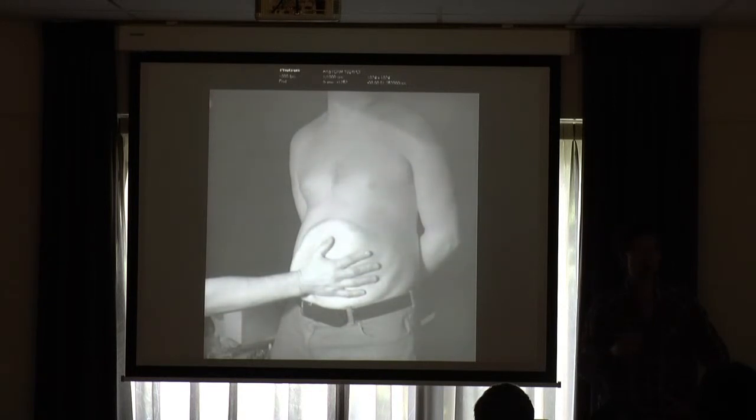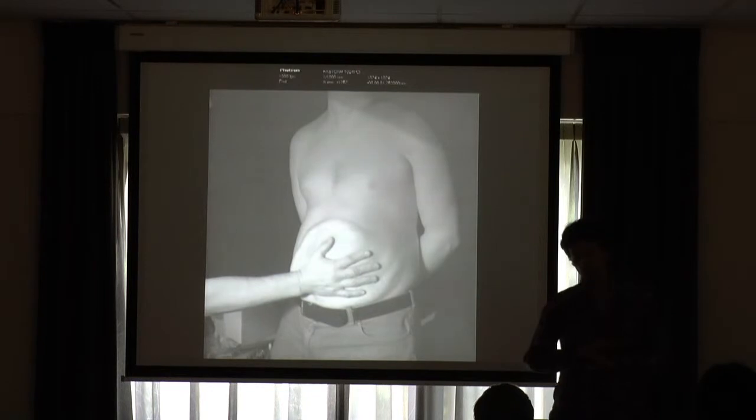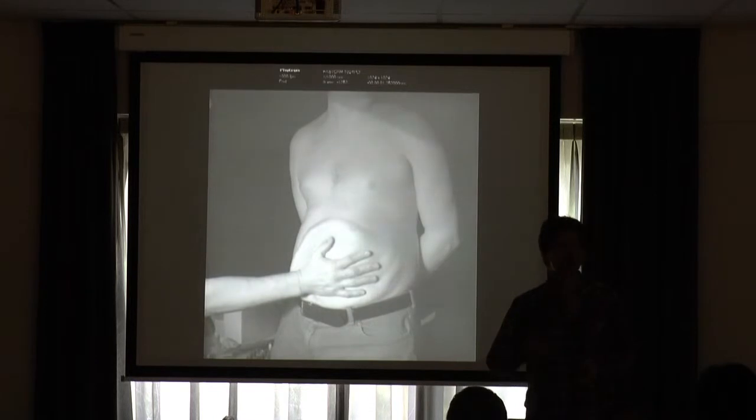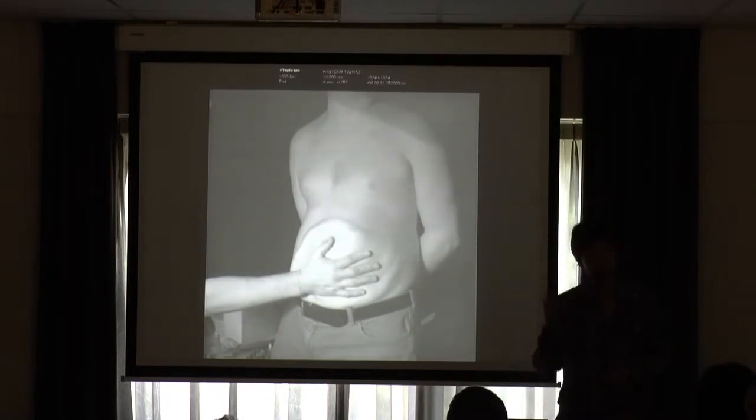And it was not possible at that time when I started my PhD thesis, because commercial ultrasound only works at 25 frames per second. This is enough for the physician to see in real time how the heart is beating, for example, but it's not enough to follow the shear wave propagation. So we had to change the way imaging echographic devices were working. And we had everything in the lab. We had the so-called time reversal mirror, which is basically electronics that can control all the transducers of a medical array. And then we totally changed the way imaging was done, and we could reach frame rates as high as 1,000, 10,000 frames per second.